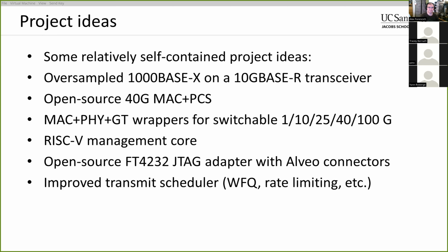Right, makes sense. A couple of options there. Another thing you can do, depending on how we set things up, is potentially have the driver or user space tools overwrite the firmware in the block RAM via a debug interface.